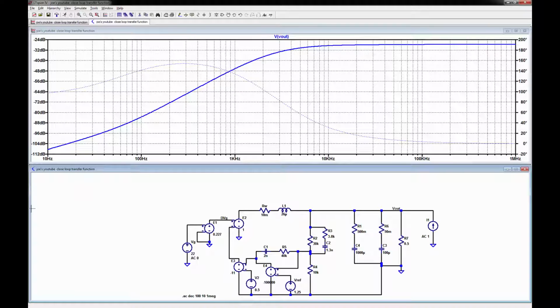Now, we want to do an open loop. That's okay. How do we open the loop? We broke it here. Remember, the output impedance in open loop is not going to be divided by 1 plus T. So this should be a lot higher over here. Not here, because at high frequency it's the same, because the loop gain's gone. When the loop gain's gone, the open loop output impedance is equal to the closed loop output impedance. Makes sense. Because you're plotting 1 over 1 plus T, and T ends off here.